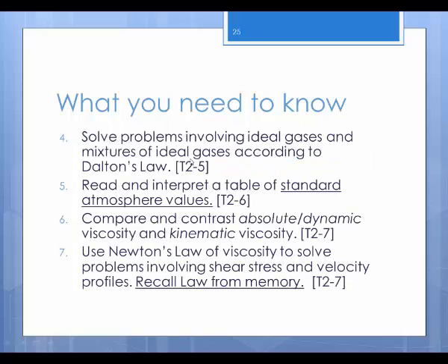Understand the ideal gas law and Dalton's law, especially how the ideal gas law will help you find density and specific volumes of gases. Be able to read and interpret values off of the standard atmospheric values and think about applications at higher altitude where those will matter. You need to understand how to calculate dynamic viscosity from kinematic viscosity and kinematic viscosity from dynamic viscosity, and know the different units. Be able to just look at something and say, aha, that thing is 0.005 centimeters squared per second. It must be a kinematic viscosity because only those have units of length squared per second, or length squared per time.